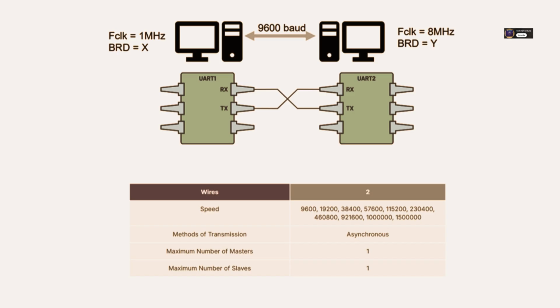Indeed. And what's fascinating, I think, is the contrast. On the surface, UART looks simple: connect a few wires, set a speed, send bytes. But as we've seen, getting it right requires careful attention to those details: the framing, the exact timing, handling potential errors, managing the data flow. If any of those are off, things just don't work reliably. It really raises an interesting question, doesn't it? If even this relatively straightforward serial protocol has these critical nuances and relies on unseen agreements like matched baud rates, imagine the layers upon layers of complexity involved in the high-speed wireless communication like Wi-Fi or Bluetooth that we often just take for granted. That is a really powerful thought.